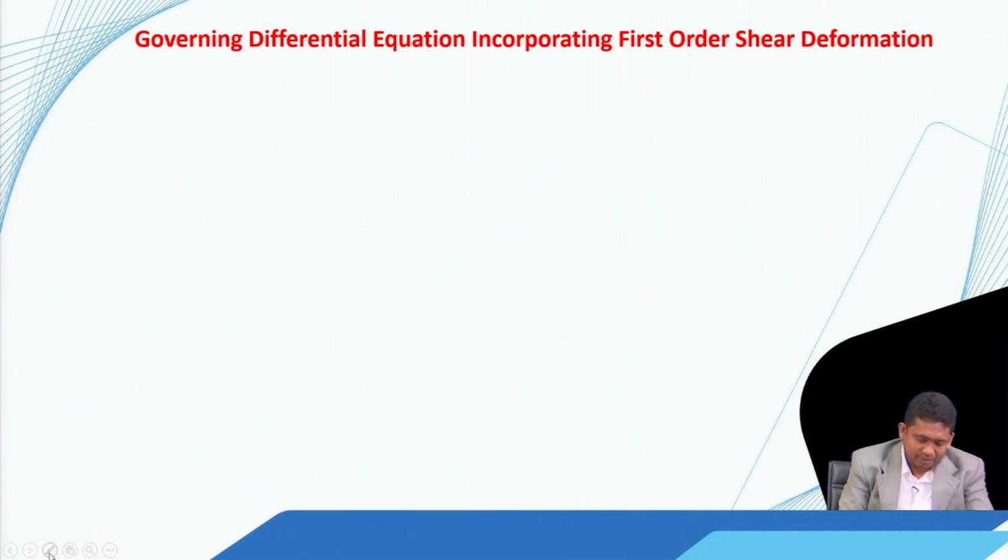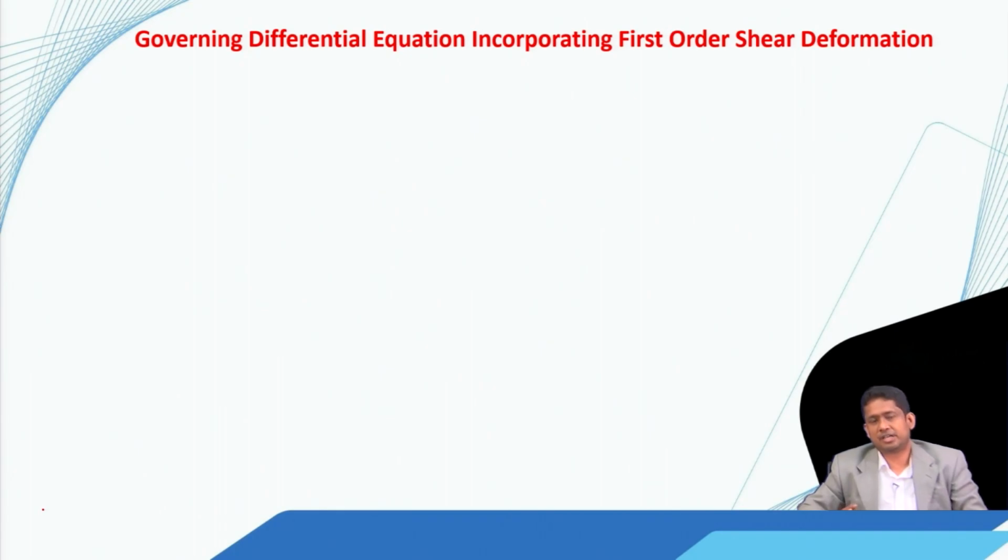When we dealt with the classical laminate theory, we derived 5 equations. First, the in plane equations along x and y, then an out of plane equation, balancing the forces along z direction, and then 2 moment equations. We substituted the 2 moment equations in the out of plane equation and got one equation. That way we eliminated 2 equations and dealt with 3 equations. Now, here we have 5 variables, so we will deal with all the 5 equations.